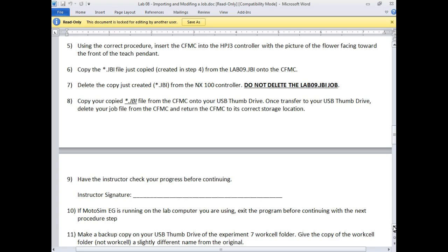You're going to modify a program, and it's going to be under a different name, because when you go over there and upload it to the robot, it's got to have a different name than a program that's already on the controller. So number one, you're going to make a copy on the controller with a different name. You're going to take the copy that you made from the controller and transfer it over to your computer.